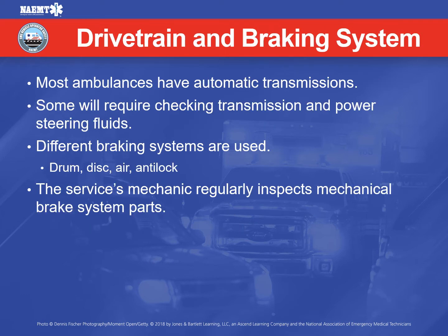Most ambulances have automatic transmissions. Some will require checking the transmission and power steering fluids. The transmission fluid is checked with the vehicle running in park, and the power steering fluid is checked with the vehicle turned off. You need to follow your service's SOPs, standard operating procedures, on filling these fluids if found low.